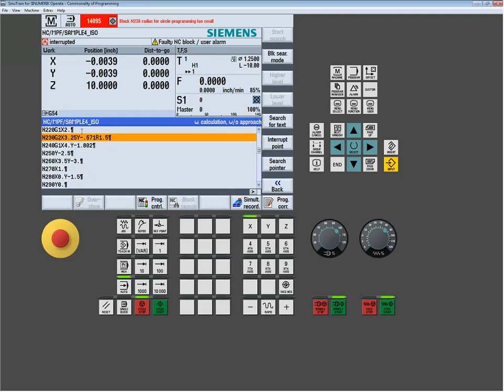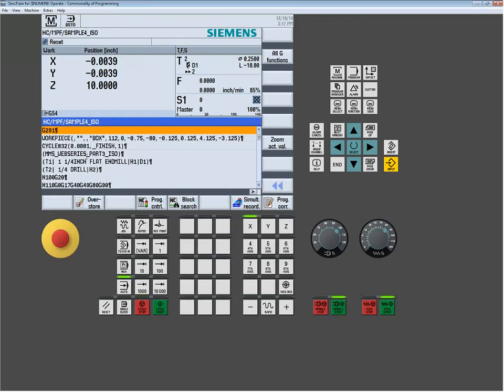You want to be a little careful when you're in ISO mode. There are things that start to get restricted when you're working within this mode. You have to be a little bit safer. But absolutely, you can certainly use it to utilize existing programs. What I wouldn't do is use this as a shortcut to get a post for my machine. If you're going to develop a post, develop within the Siemens protocol and use all of our functionality. But if you've got libraries of stuff already created, G291 is kind of the way to go.